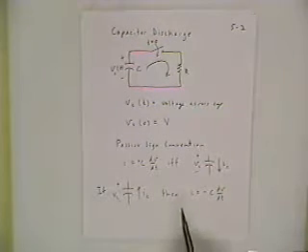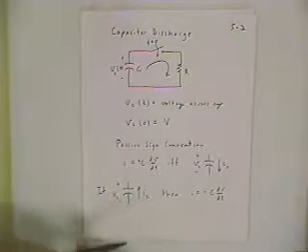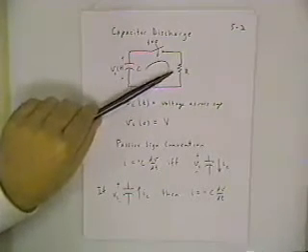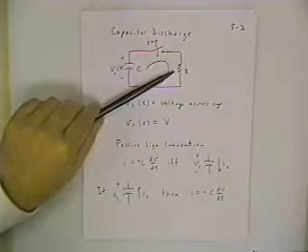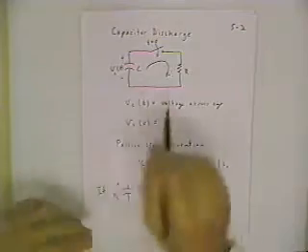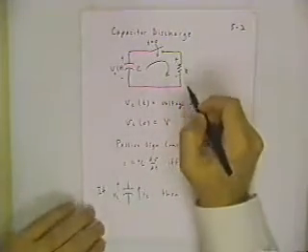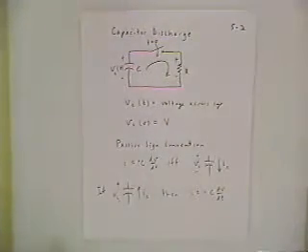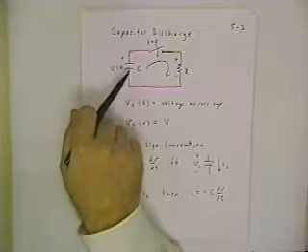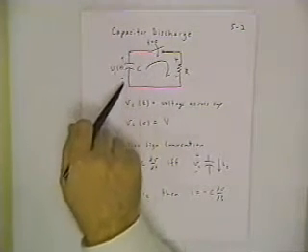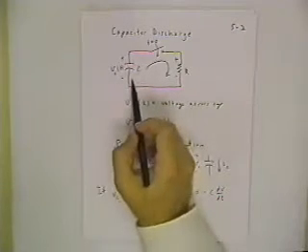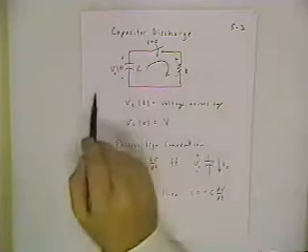And that has to do with the energy flow in the capacitor. Compare with a resistor, where power in the resistor is always V times I, and it's always going to be voltage with plus to minus polarity matching the direction of current flow. For a capacitor, if that capacitor is charging up, the current's going from higher to lower potential. But in this case, the capacitor is discharging, so the current's actually going from lower to higher potential.